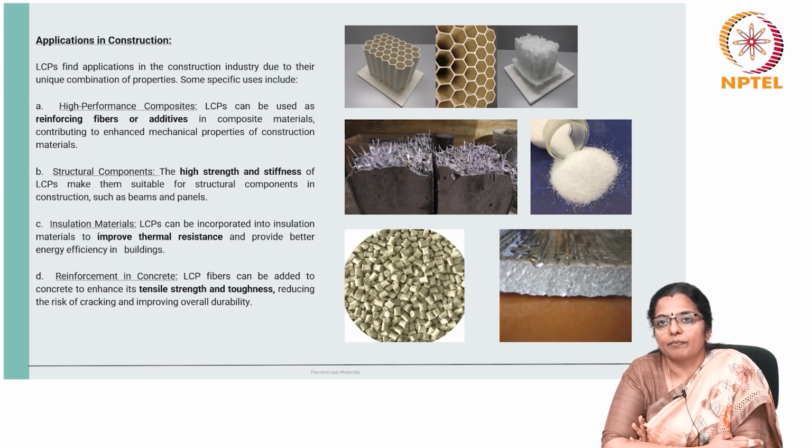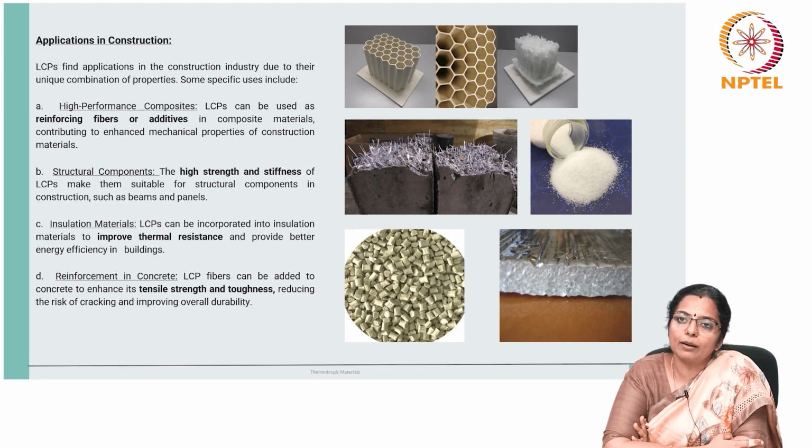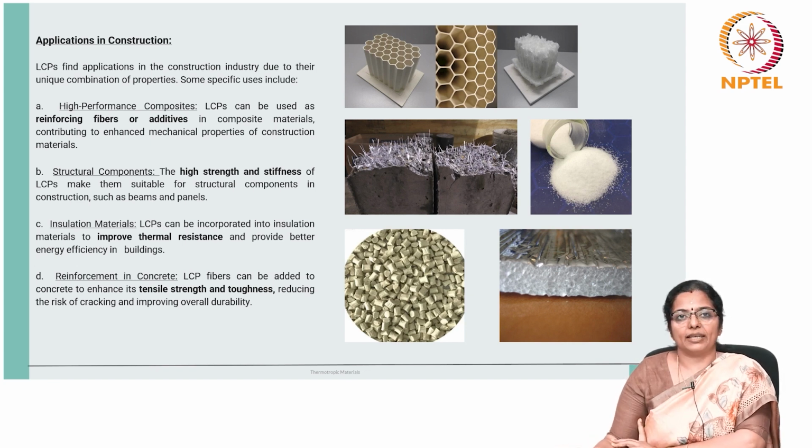Insulation materials. LCPs can be incorporated into insulation materials to improve thermal resistance and provide better energy efficiency in buildings. When it comes to reinforcement in concrete, LCP fibers can be added to concrete to enhance its tensile strength and toughness, reducing the risk of cracking and improving overall durability.